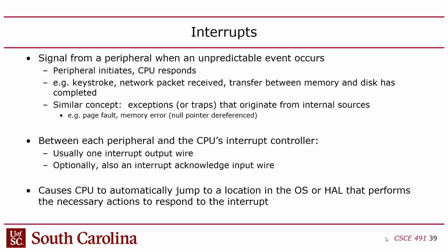But the idea is that this peripheral can interrupt the CPU, which then runs an interrupt service routine, which deals with the interrupt somehow. Typically, the number of interrupts is limited. You don't necessarily have a dedicated interrupt for every peripheral. It depends on the system. But if you have, say, one interrupt that covers multiple peripherals, then the CPU would have to interrogate the peripherals to figure out which one requested the interrupt after the interrupt is serviced.